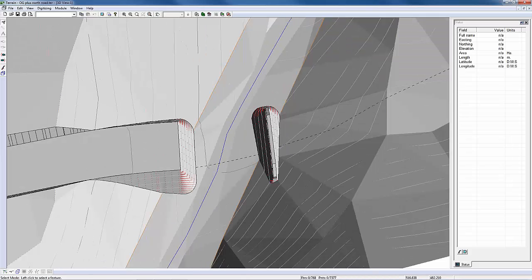Okay, let me just do a quick recap of what I've done so far. The question was, can you mask the grading slopes at a particular side? Yes, you can. And the second question was, is there any option to introduce multiple grading slopes, benches within the slope? Yes, you can do that.